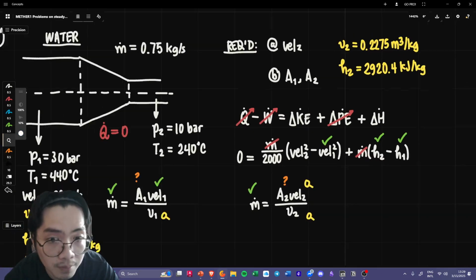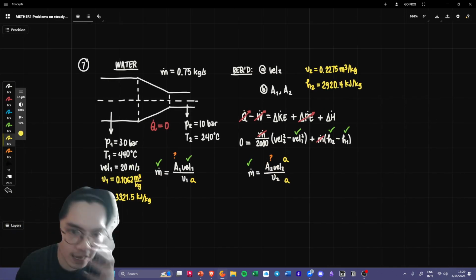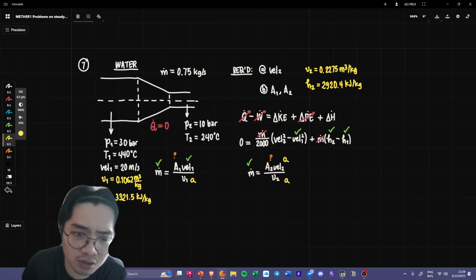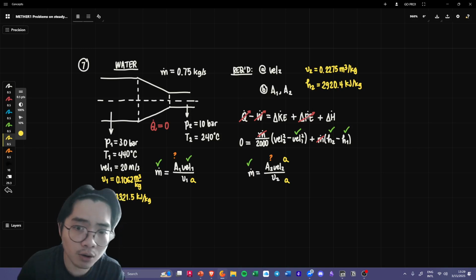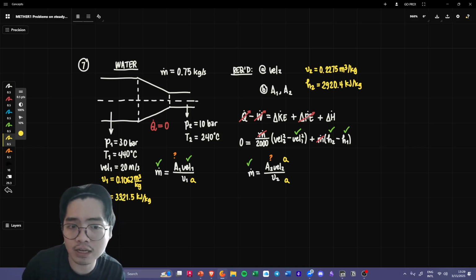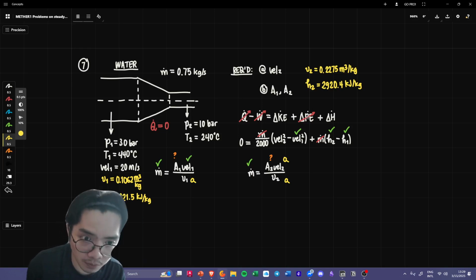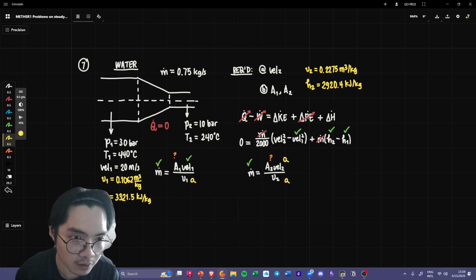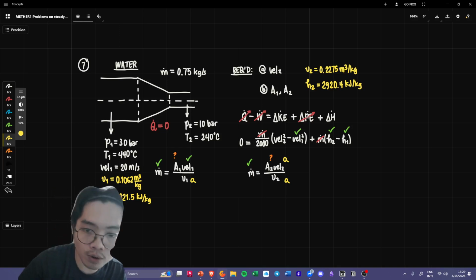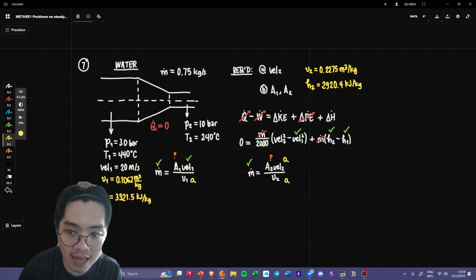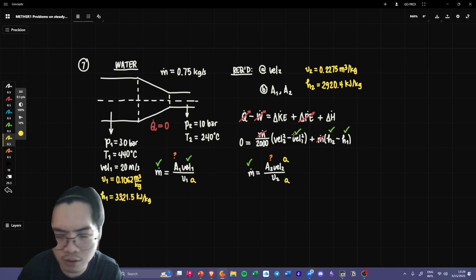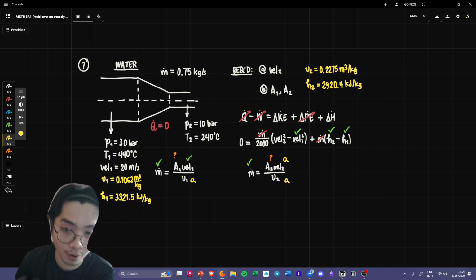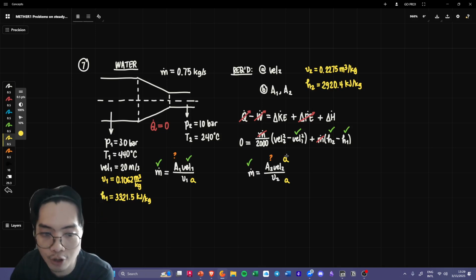And so now, my advice to you guys is that whenever you're looking at a nozzle and a diffuser, it's very tempting to just go like, oh, it's just conservation of mass, right? But always remember that change in energy has to go somewhere. And usually that has to do with the change in kinetic energy, right? So if you're trading it for lower pressure, that must mean that you have higher speed, right? You will also learn about this in fluid mechanics, but I'm not the prof there currently. So there you go, right?